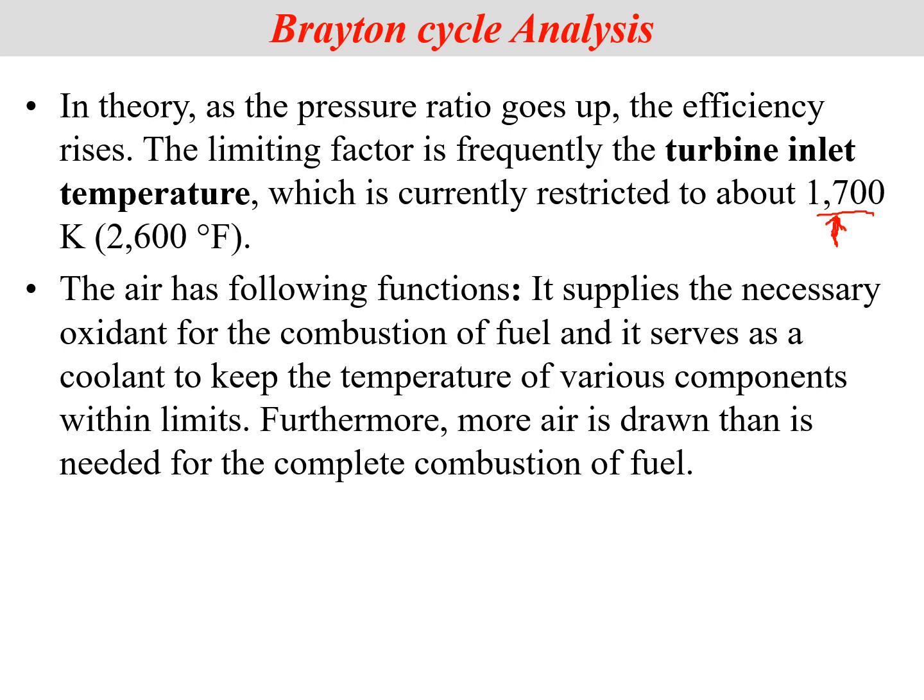So what we do is we just inject fresh fuel into the exhaust of the turbine and burn that. That does not come in contact with the turbine or the original jet engine. It just burns and produces an effect like a rocket. Like when you suddenly push exhaust gases out of a rocket, it pushes the aircraft in the opposite direction and you go much faster, sometimes even faster than the speed of sound.